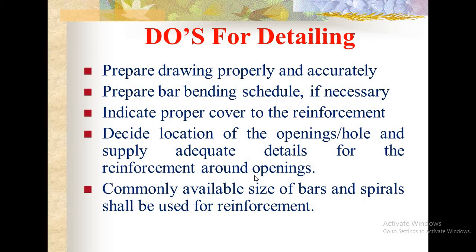Prepare drawing properly and accurately. Prepare bar bending schedule if necessary. Indicate proper cover to reinforcement. Decide location of the opening and holes and supply adequate details for the reinforcement around opening.